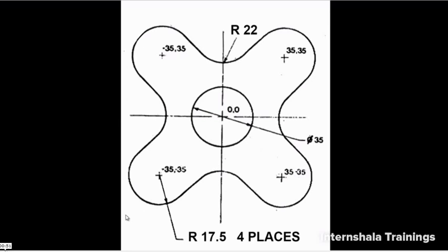So I'll give, say, minus 60 as the lower left, and the upper right should obviously be 60. So likewise, by setting the lower left at minus and upper right at plus, you could bring all the 4 quadrants within the screen. So that is how the limit for this particular figure is set.